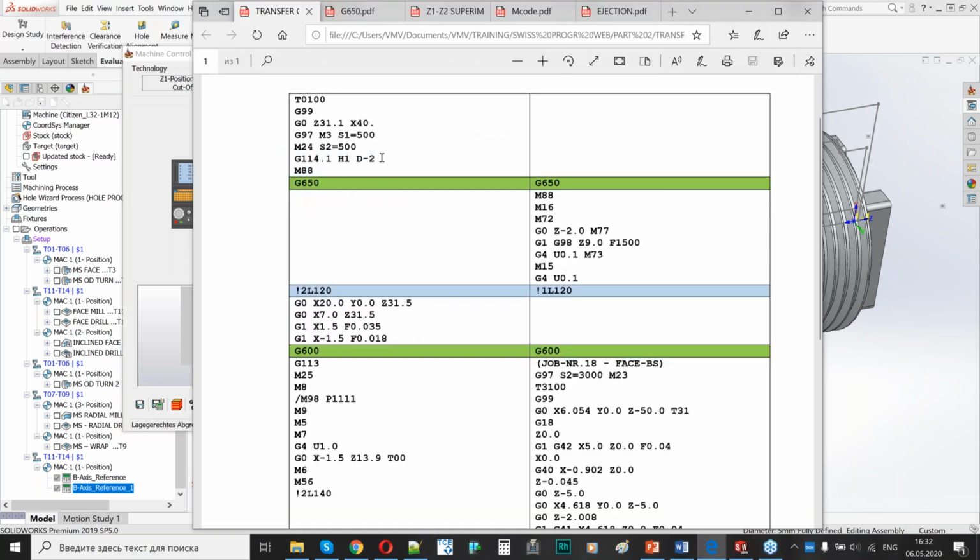The next two parameters are about this code. It's a synchronization type. It's a little bit complex. It has different values here, but you can apply different types of synchronization. Inside the Mitsubishi CNC, you can apply both synchronization of speed and synchronization of phase.